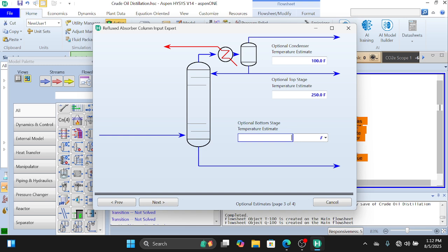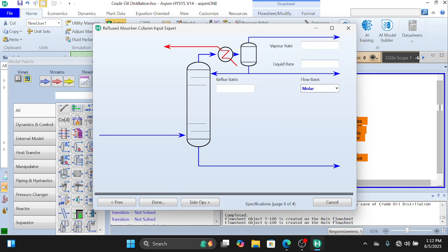So we have the temperature at 700 Fahrenheit. Okay, the vapor rate is going to be 0. We change this to mass, and then we're going to work in the reflux ratio of 1. Alright, so this is actually the same thing what they have in theirs, still 0 0, and then we have the reflux ratio different. They didn't specify the basis of their mass of their own reflux ratio, but we had to specify this as the volume.